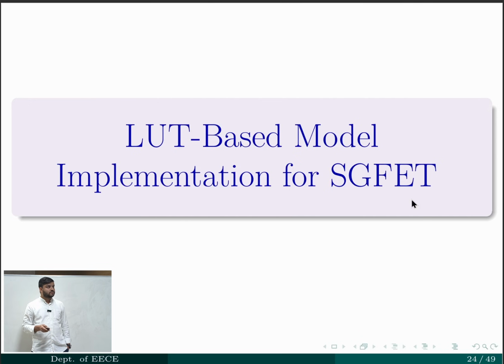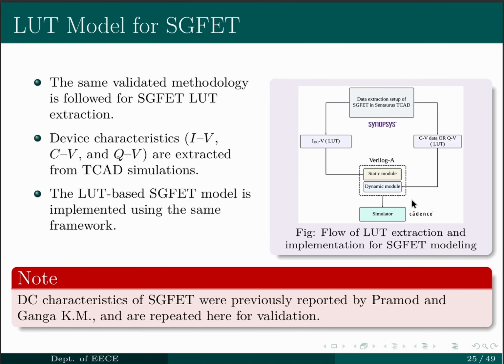Now, I am going to show the LUT based model implementation for SGFET. It will follow the same flow. In the case of SGFET, the device is first simulated in Synopsys TCAD. From there, dynamic and static data is stored in the form of a LUT, and the LUT is also given to the simulator. In this case, the simulator is Cadence.